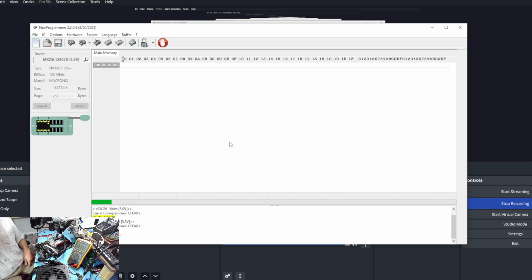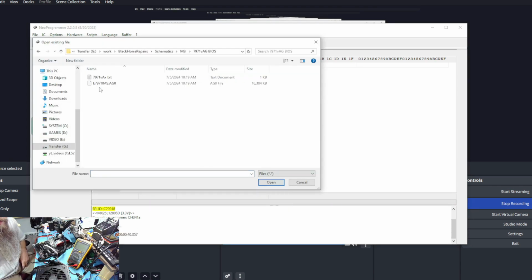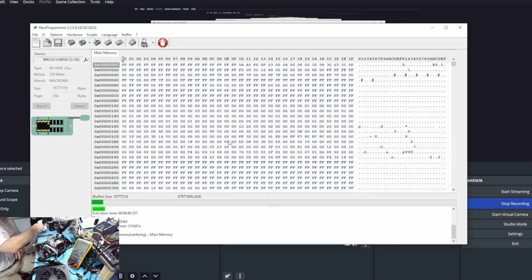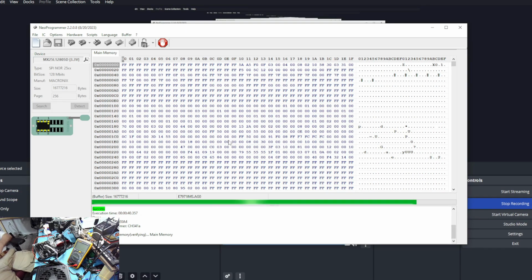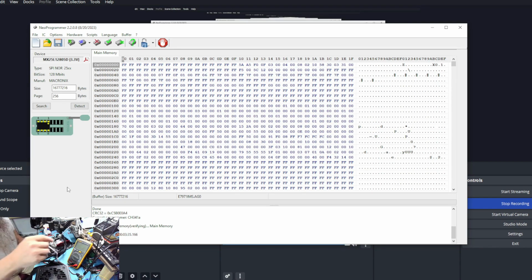So I'm just gonna erase the chip and upload the BIOS that I downloaded from the MSI website. Alrighty, we are updated.